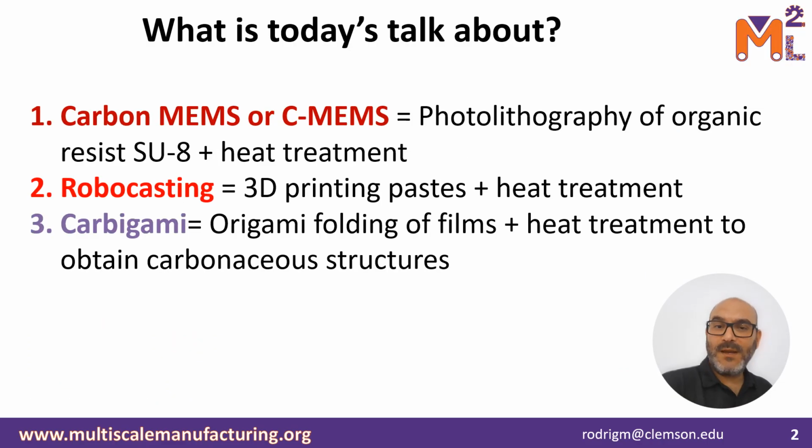So what is today's talk about? We will be addressing three different approaches to shape a polymer that we will carbonize. The first one will be carbon MEMS or CMEMS, as you already know from previous sessions, which is the photolithography of organic resist followed by the heat treatment.